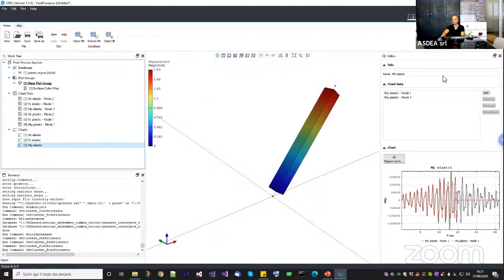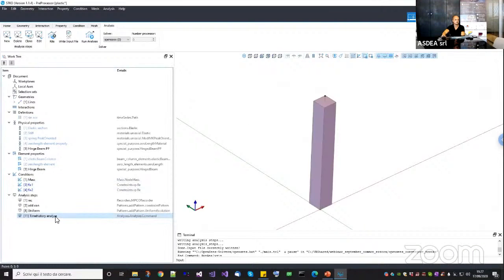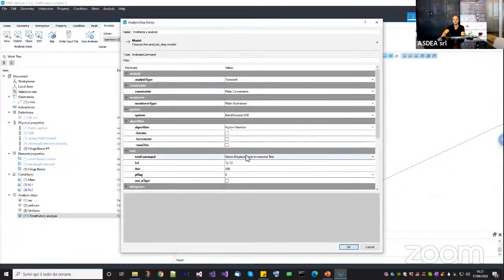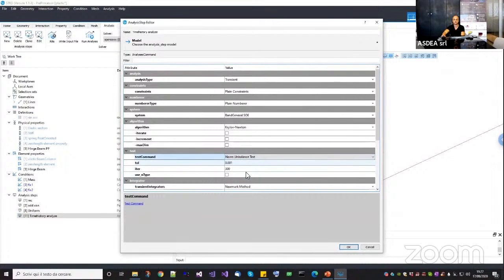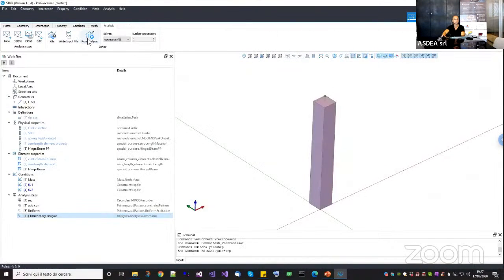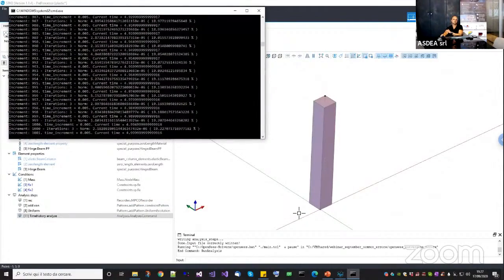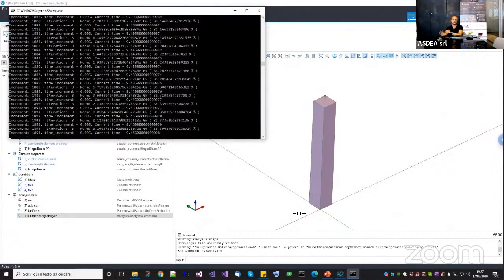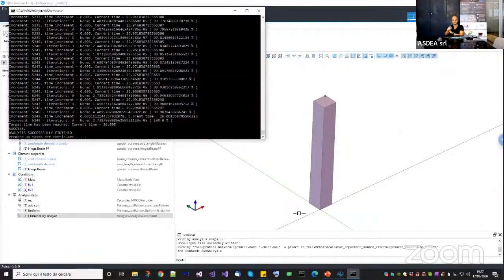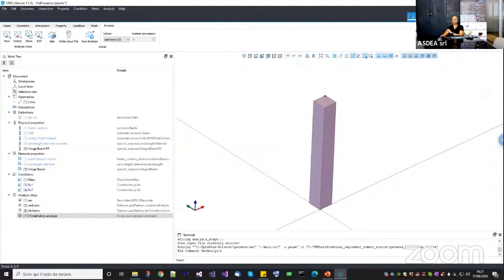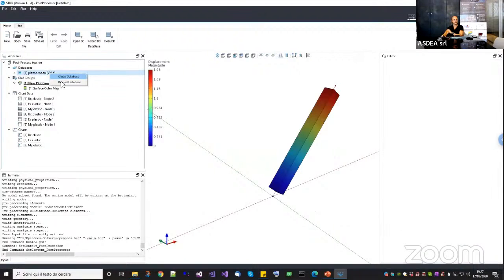And as you can see, I have a complete zero. So here I have two options. Once again, I can keep on decreasing the displacement tolerance because probably 1 to the minus 12 is still too high, or I can use the norm balance. Okay, now let's try to use the norm balance and let's see what happens. Basically, in this case, when you have stiff problems like this that are very stiff at the beginning and then very flat, probably using the norm balance is much better. Okay, so I just reload it.